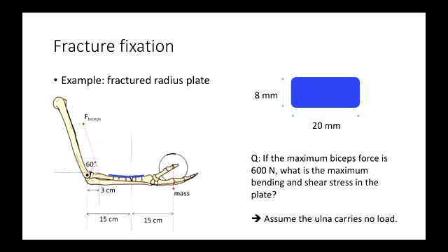So for that plate, the top is being stressed in tension, and the bottom half is being compressed. Does that make sense? Okay, so the maximum stress will be in both different directions, at the top surface and bottom surface. So plugging into that formula, sigma equals M times y, 7800 times y, so that's half the thickness, so 4 mil, divided by I.